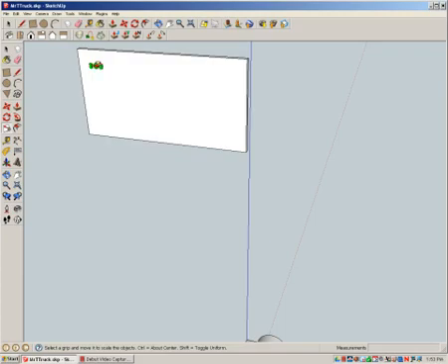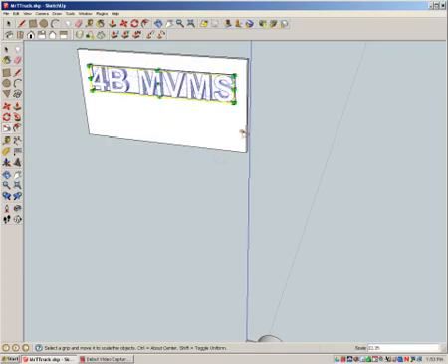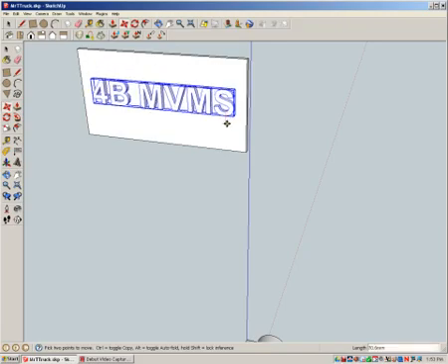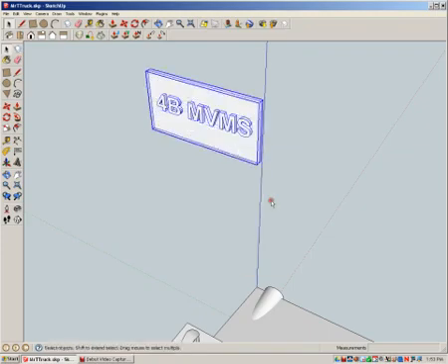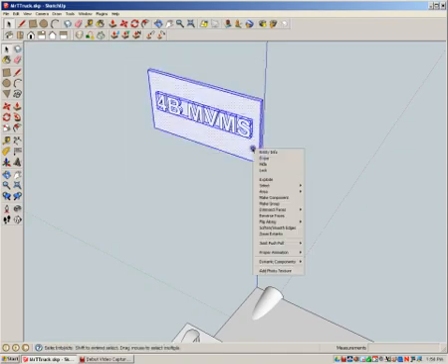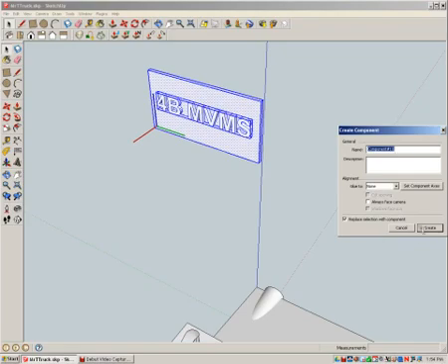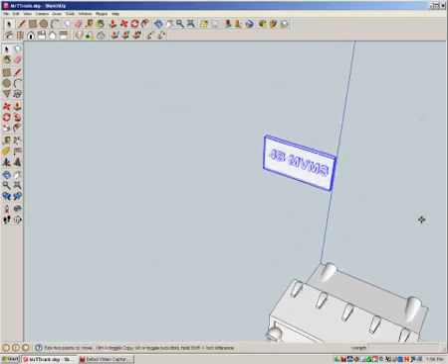Easy to fix. Grab our scale tool and pull it out big, move it down to where it's centered. We could color the license plate. Let's make this whole thing one component. Whoops, it's not what I wanted. Control Z, make the whole thing a component.